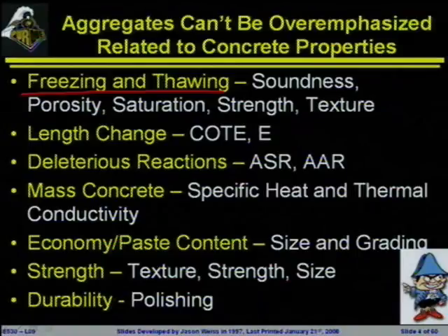That is a problem called D-cracking that we will talk about a little bit later. That's a fairly common problem where the aggregate itself isn't resistant to freezing and thawing. And this is a big issue, and this drives a lot of how aggregates are looked at and how aggregates are brought into the mixture.